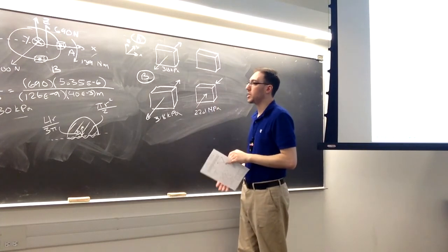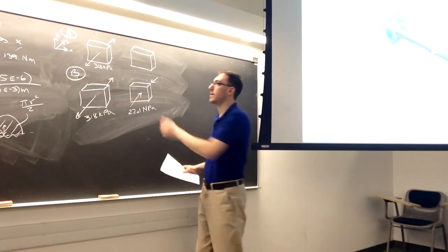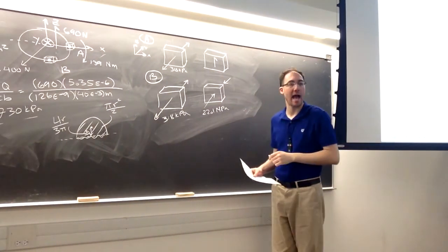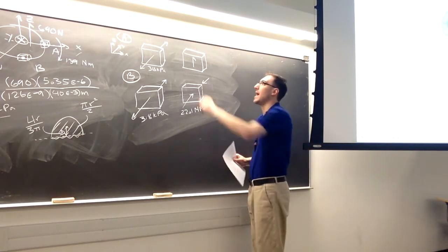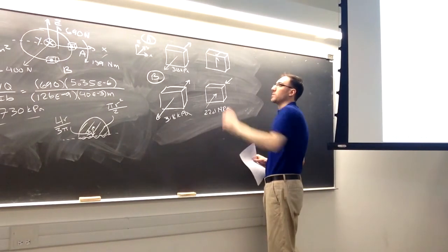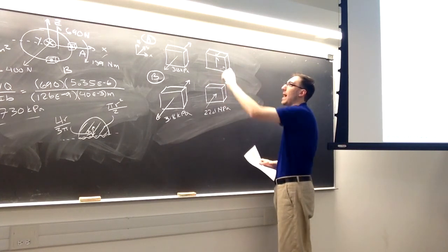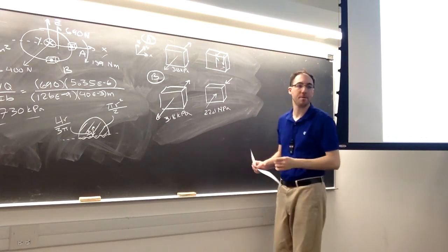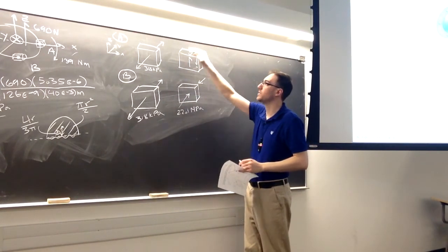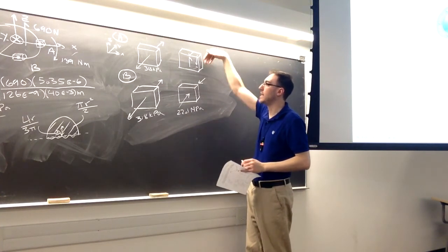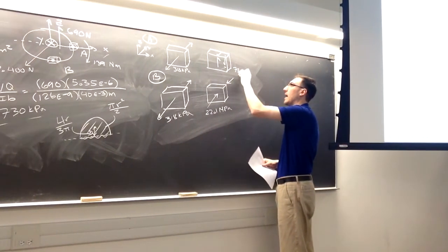So how do I illustrate this shear stress on the cube at A? It's going to be in the same direction on that front face as the shear force. So it's up. And because it has to be in equilibrium, I now know the directions of the other shear stresses: they have to meet in the corners. So on the bottom, we'd be going back. On the back side, we'd be going down. So really, we can only see the front and the top from this picture. The front goes up, the top goes forward, the back goes down, the bottom goes back. Again, 730 kilopascals.